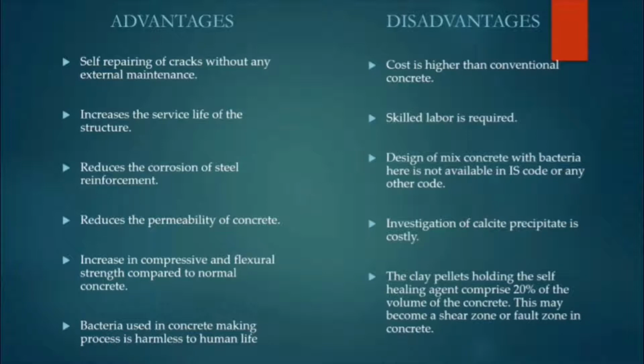Design of mixed concrete with bacteria is not available in any IS code or any other code. Investigation of calcite precipitate is quite costly, and the clay pellets holding the self-healing agent comprise 20% of the volume of the concrete, and this may become a shear zone or fault zone in concrete.